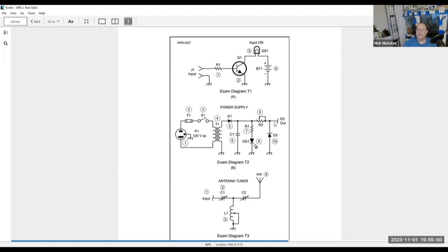Zener diodes are built, when you buy them, by voltage value. So if you need to regulate a 6-volt circuit, you get a 6-volt Zener diode. If you control the current just right, that diode will regulate the output very, very well. If the current capacity that you need is greater than that one diode can handle, then you amplify it with a bunch of transistors. They're called pass transistors when you do that.